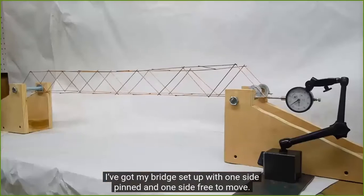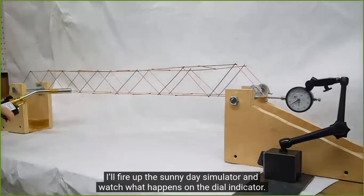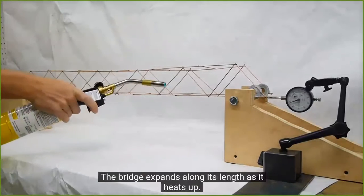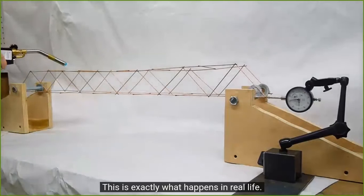I've got my bridge set up with one side pinned and the other side free to move. I'll fire up the Sunny Day simulator and watch what happens on the dial indicator. The bridge expands along its length as it heats up. This is exactly what happens in real life.